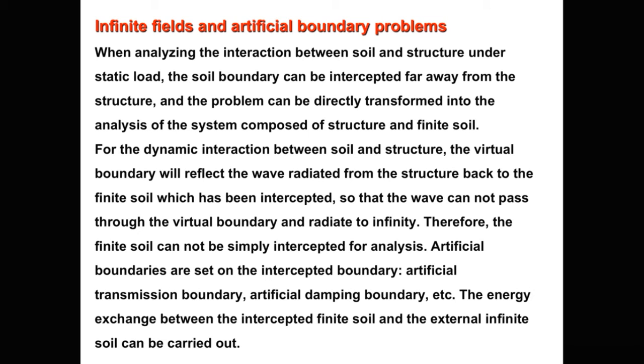However, in the dynamic interaction between the soil and the structure, the virtual boundary will reflect the wave radiated from the structure back to the finite soil which has been intercepted, so that the wave cannot pass through the virtual boundary and radiate to infinity. Therefore, the finite soil cannot be simply intercepted for analysis.